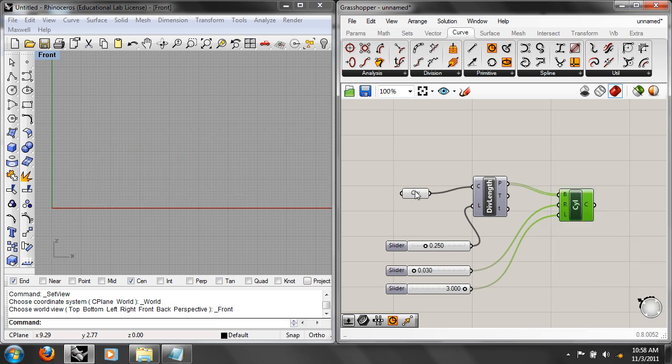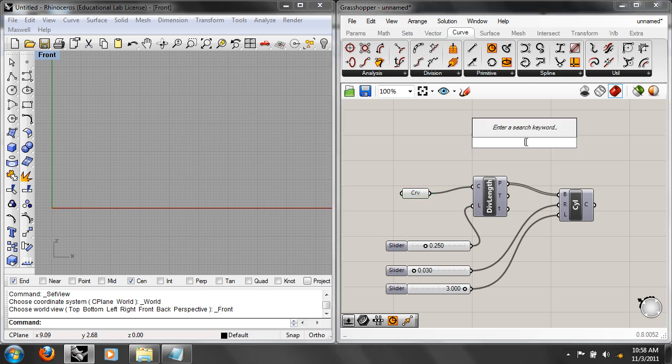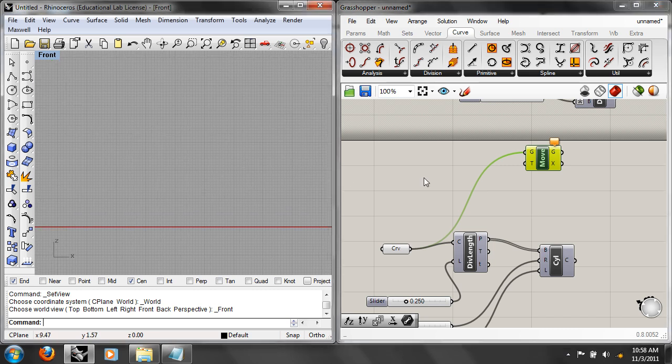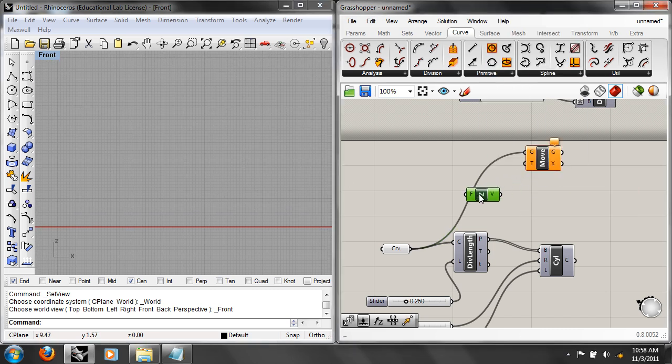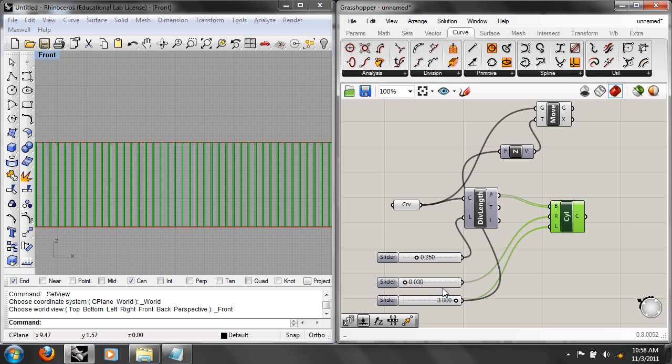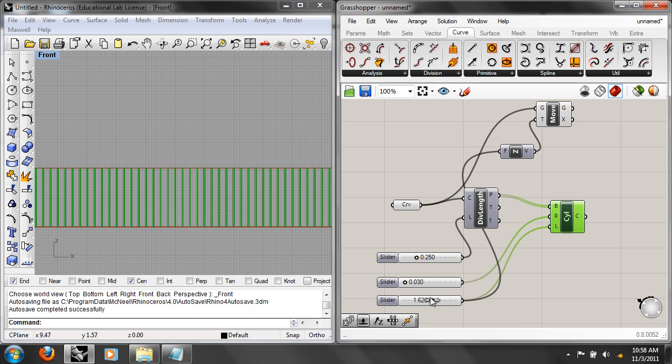If I have a line on the bottom and I want it here, scale it, or move it. Move it. Yeah, right, because move is going to change the state of it. So let's take that curve, let's move it, and we're going to move it in what direction? Yeah, up, Z. Up and Z. And what's the height of that? What should I plug into this to get the height of it? Height of the cylinder, yeah. So now, if I look at my thing, right, it's parametric. That's the height of the railing, okay?